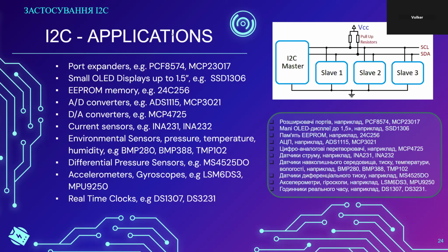This device, or similar devices, are generally interfaced by I2C interfaces. And they are not too slow. This is data that changes in the range of milliseconds. So the I2C interface at 100 kilobits per second or 400 kilobits per second is very much fast enough. Even though it is technically a slow interface, it is fast enough to read out data from pressure sensors, even from drones in flight for airspeed measurements.